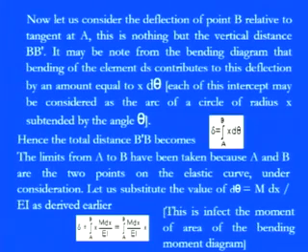So now you have two main equations: one is the theta equation, θ equals the integration of M dx divided by EI, and the delta equation, which is the integration of M dx by EI times x.